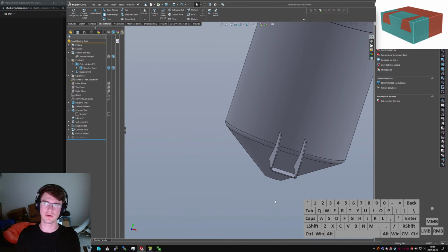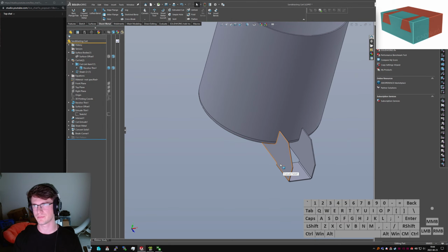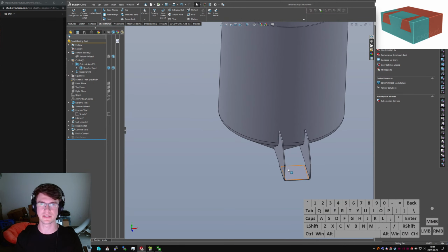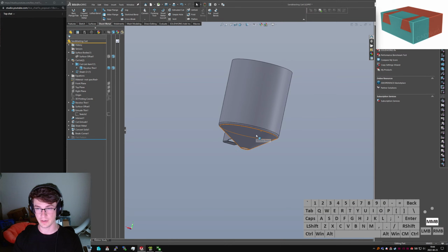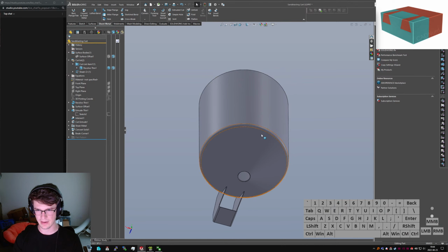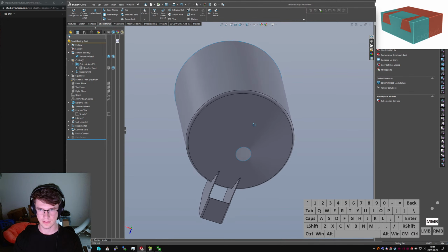If you wanted to be clever, you could probably drill it out oversized and then use maybe a nut welded onto the backside if you were manufacturing this on your own. In a production environment, even better, a form tapped hole through the part would be the right way to go. That would give you something both nice and stiff. It would be efficient and cost-effective from a manufacturing perspective. Now the trickier part is coming back here and coming up with something that meets up with that. So we'll show the surface part again and hide the non-sheet metal part.